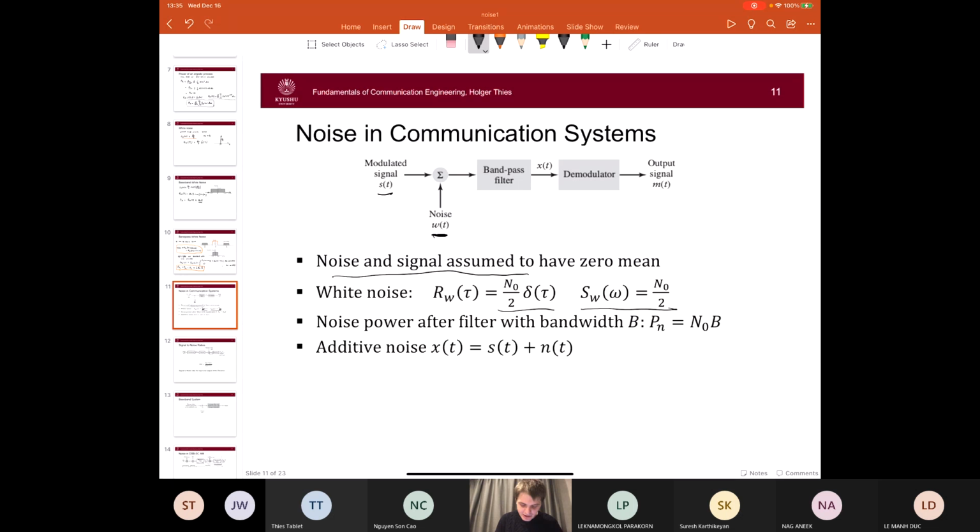And then, a communication system. The first thing we will do is filter out things at other frequencies. If we send something over a channel, our signal will have some frequency components, but there will be other stuff too: noise, and there might be other processes at other frequency components. So the first thing every communication system has to do is apply a bandpass filter so that we only look at the frequencies of our signal that we are interested in, and filter out all the unnecessary frequencies.